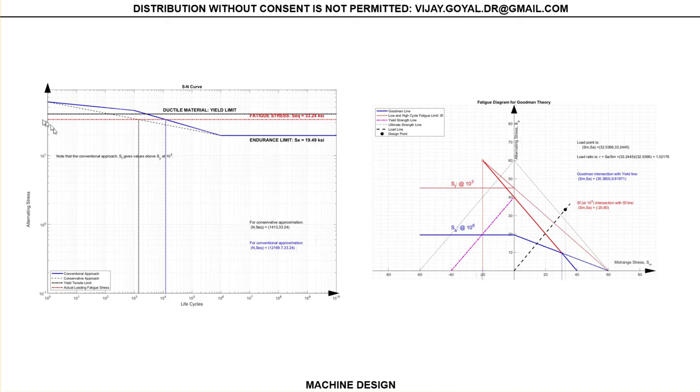Now, as you can see, this is the endurance limit, right? This endurance limit, this line actually belongs to this line over here. And any stress that falls underneath this, right, here, is the same stress that will actually fall underneath this line. As we talked about last time, anything inside this curve, right, inside here is infinite life. So anything below this is also infinite life. It kind of makes sense, right? So as we go, let's say a point is over here, and you can see my point is actually here. It says it's not acceptable, okay?